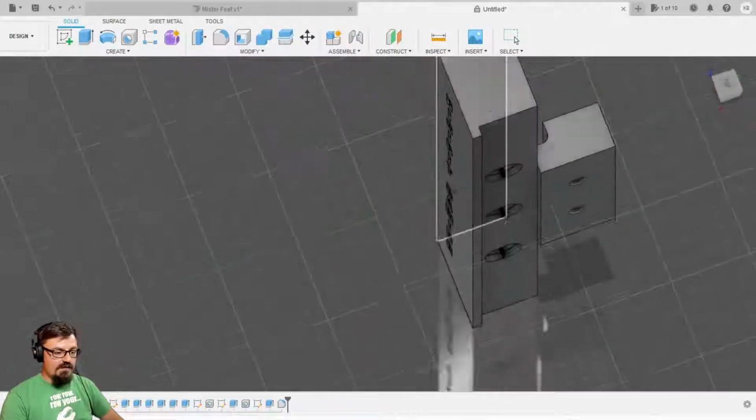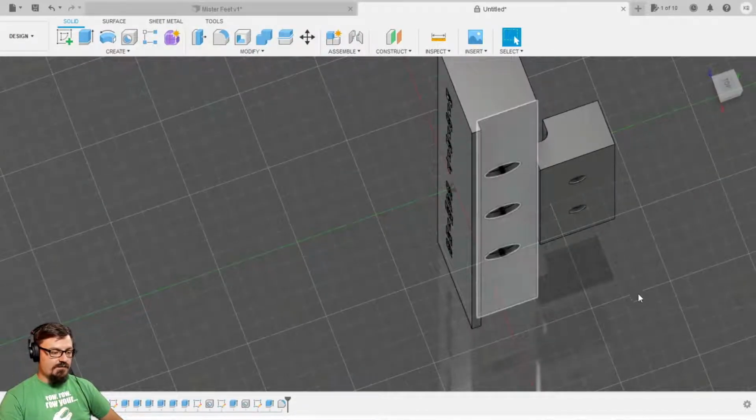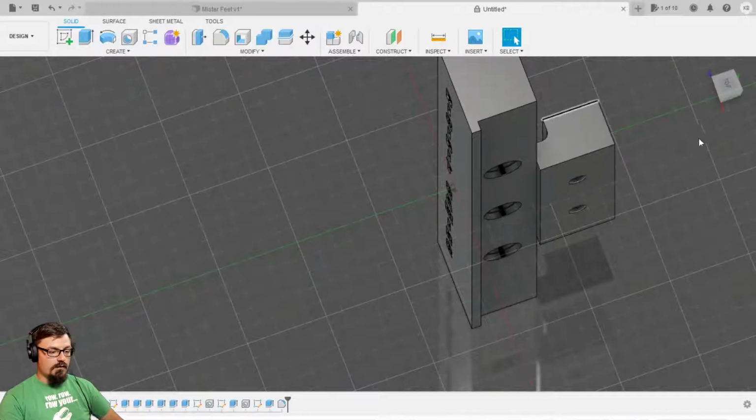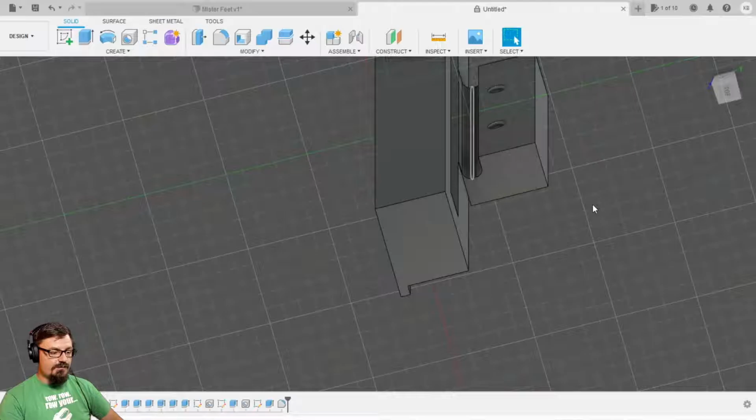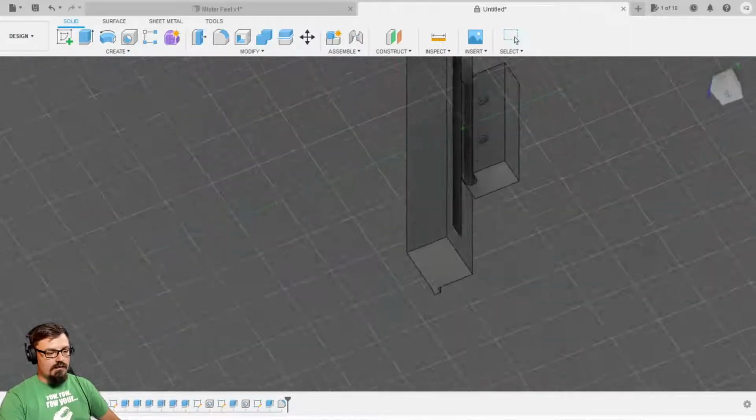So worst case scenario is you run your LEDs and then you solder on your wires, run them up, over, and around this way and through this little channel. That way you'll be able to run it to your LED controller, your hard drive LED indicator pin on the motherboard, all that stuff.